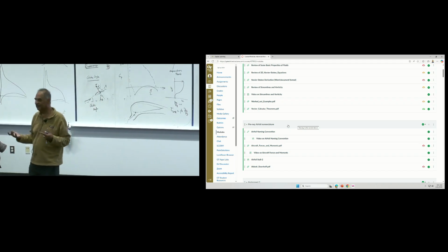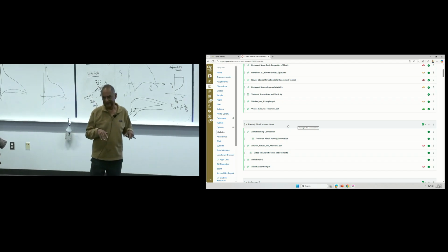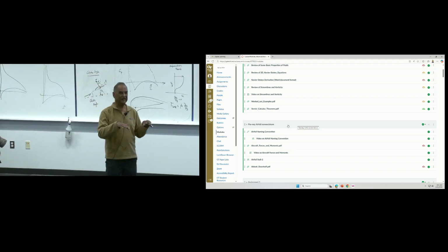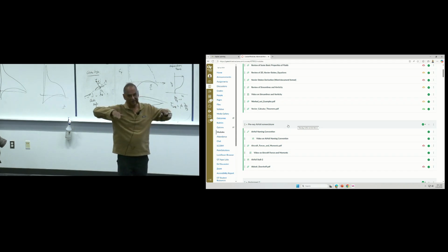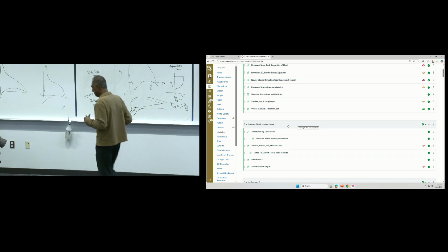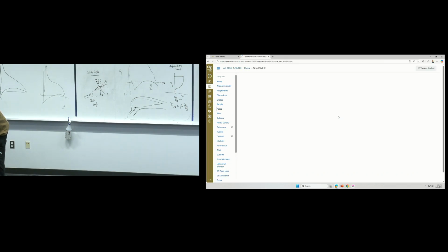They like a trailing edge stall that progressively grows because you get plenty of warning. Okay? Stall warning will say, hey, you're going to stall, reduce your angle of attack, or increase your forward speed. You want to achieve the same lift, but you can decrease the lift coefficient by reducing the angle of attack. Okay? So it'll give you that information. So in my lectures here, I have a video of airfoil stall, a very, very short video.